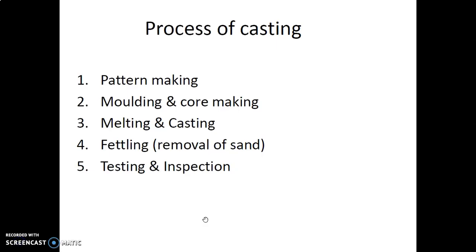In the video the casting process is very simple. Okay, but you have to follow the steps very seriously. Okay, so you will get the product without any defect. Otherwise you will get a number of defects, like some air is trapped inside the metal, or some damages, or you will get rough surfaces.